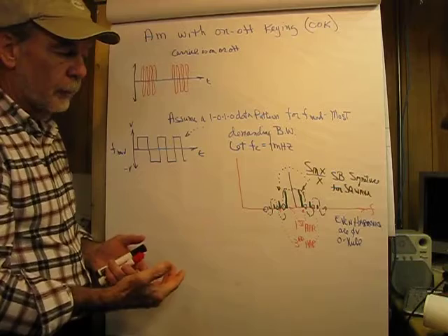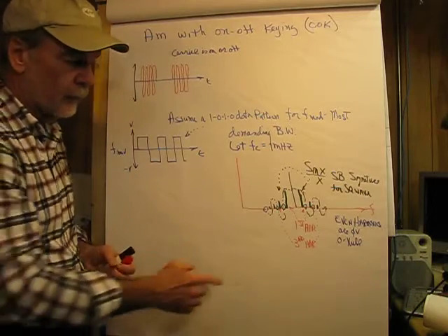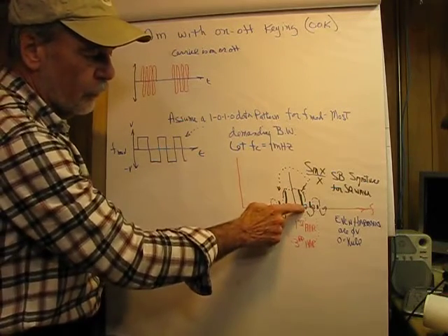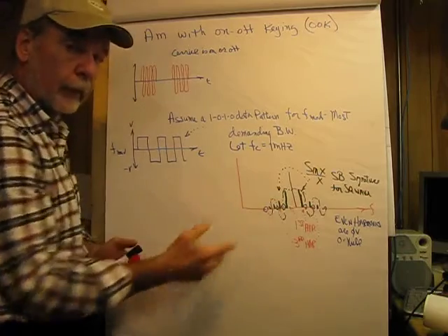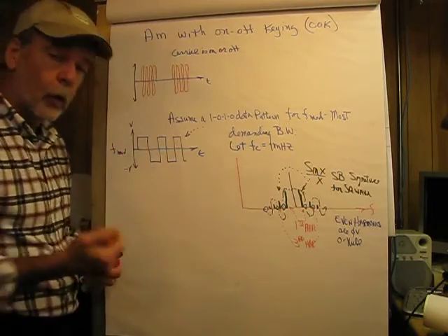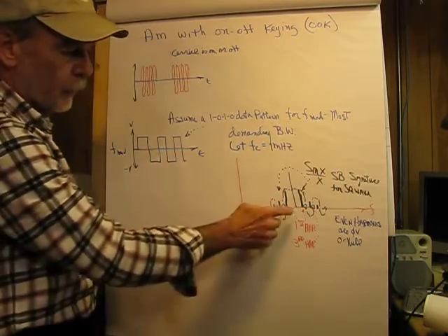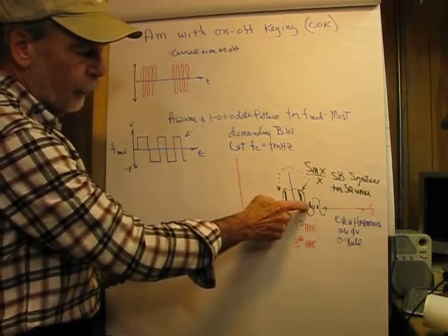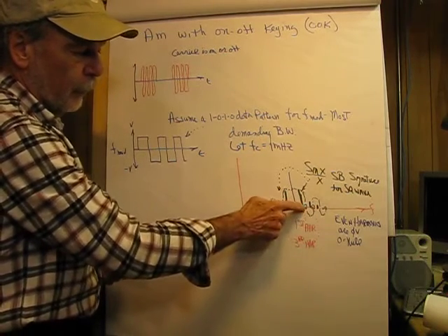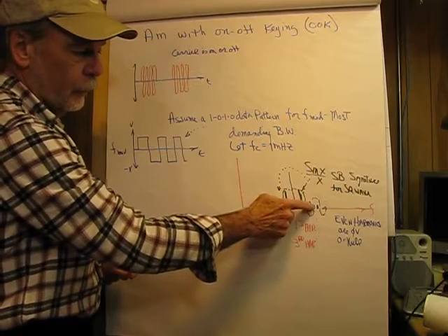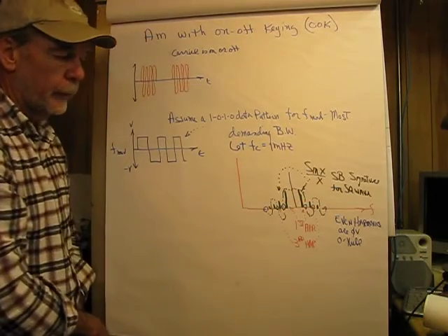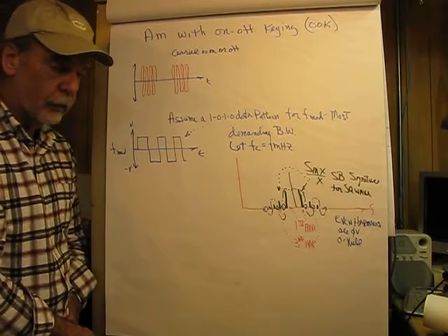Now, if I superimpose a sine of x over x on this, we see the null points. And remember that a square wave only has odd harmonics. So 1st, 3rd, 5th, 7th. The null points would be the evens 2, 4, and 6, where the harmonics would be 0.